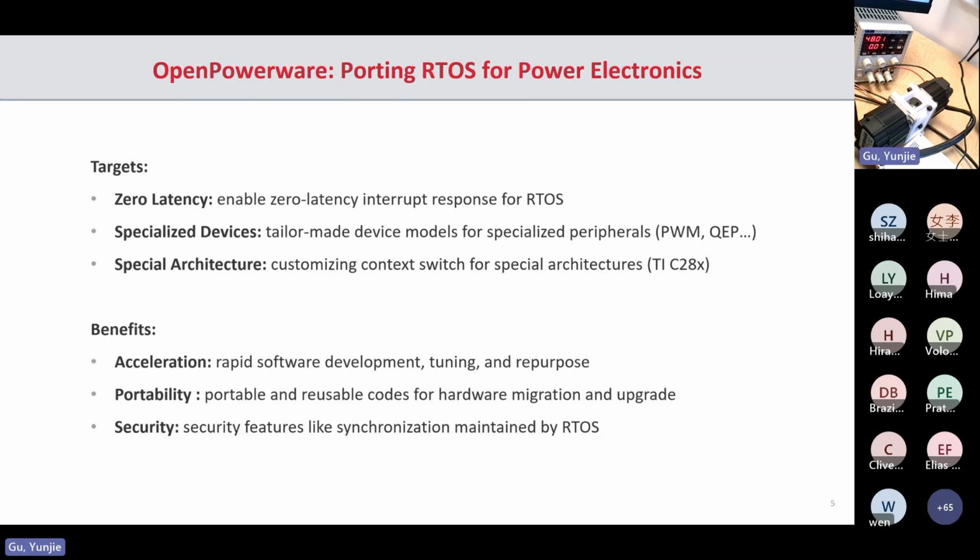features of security. And, like, the RTOS offers mechanisms of synchronization like mutexes and semaphores, which do not exist in bare metal development. In bare metal development, the developer has to think of his own synchronization mechanisms, which sometimes can have bugs inside. And these bugs are very hard to debug. So the benefit is quite straightforward. But there are also some challenges.